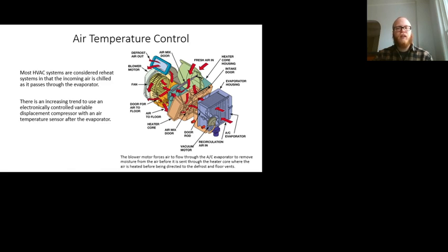Well, that condensation that builds up on an evaporator helps catch dust and other debris, and then as the water droplets get large enough to start dripping and falling off of the evaporator, they also bring all those little pollutants along with them. And also, as humans, we like it when the air is not super humid, right? We're always like, it's not the heat, it's the humidity. Well, yeah, here we go.